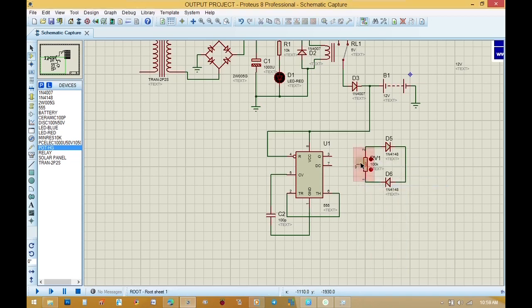So whenever you are making a design or you come across any circuits of this nature, just look at that 555 timer. Look at the configuration of pin 4 and pin 8, pin 2 and pin 6. The configuration you have there will tell you the mode that the 555 timer is configured to work as.